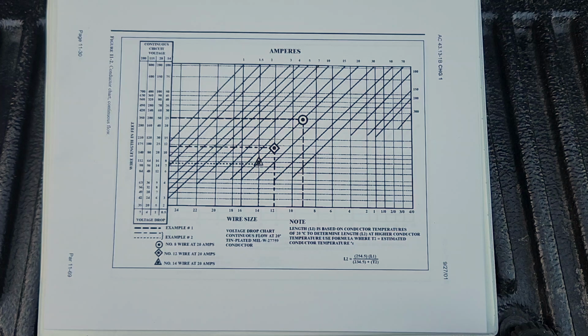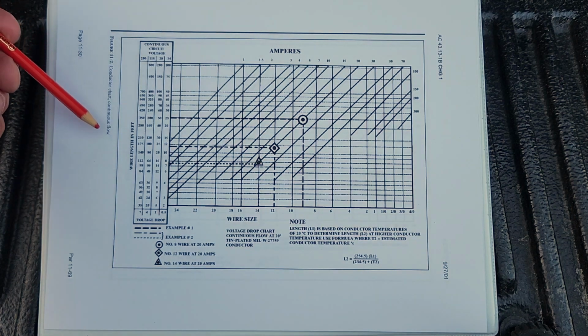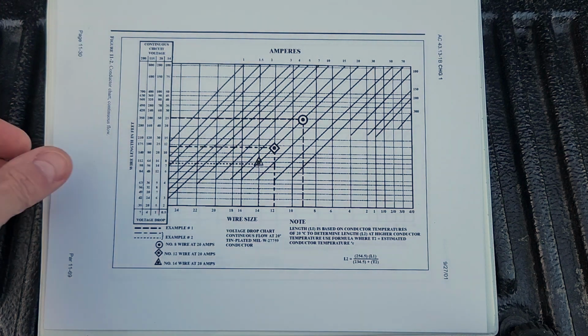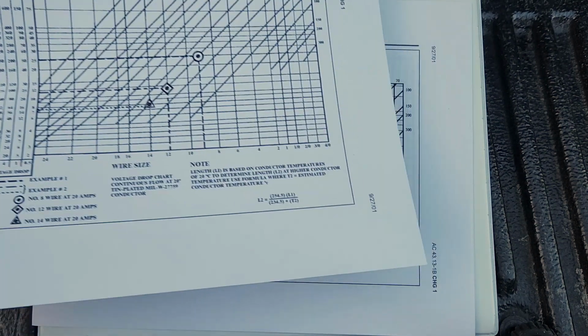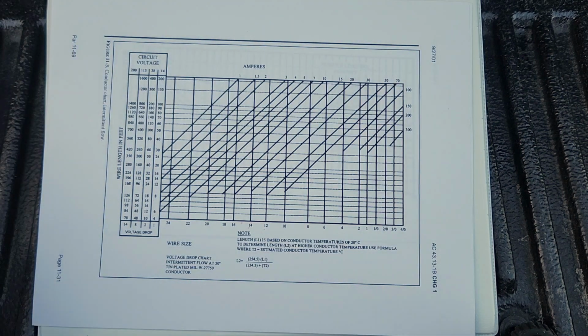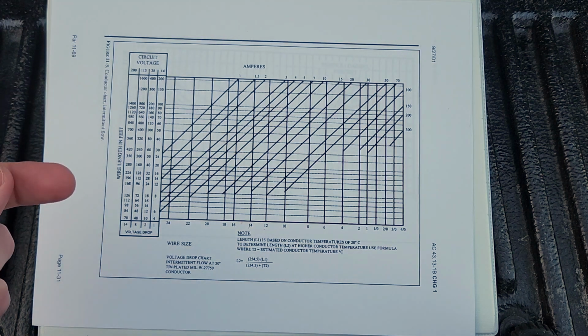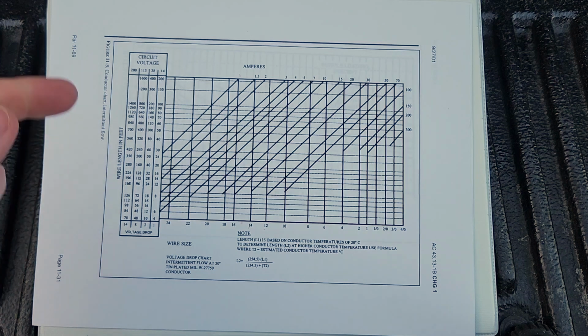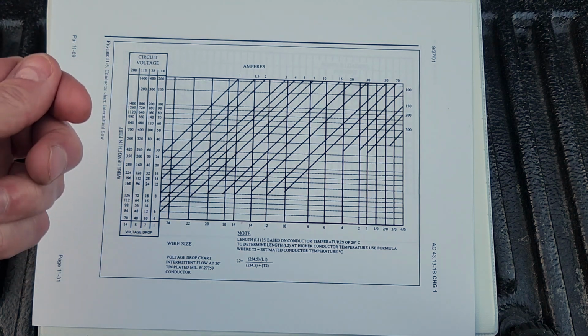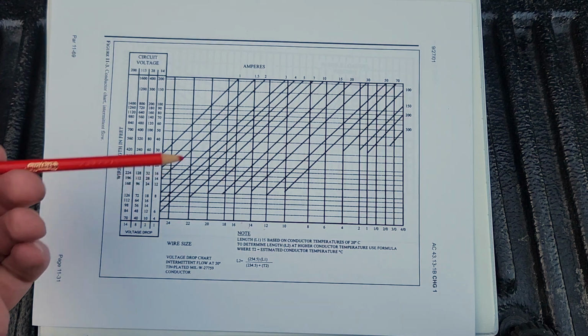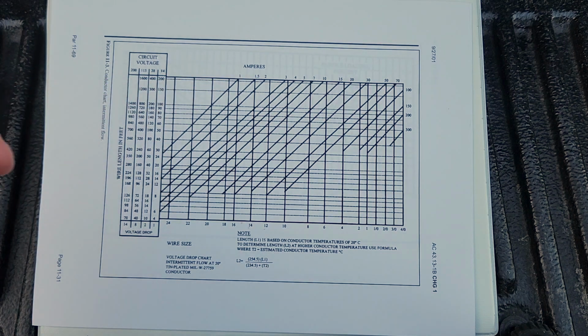This is for continuous flow, but sometimes you've got a branch circuit where you've only got, say, intermittent or peak. So you might be at 1 amp just sitting there continuous, but it might peak to say 10 amps briefly. The FAA doesn't care about voltage drop on the load so much as where that energy is going, and it's going into the wire as heat, and they're concerned about things catching on fire. So for brief periods, they're willing to let you pull more current.